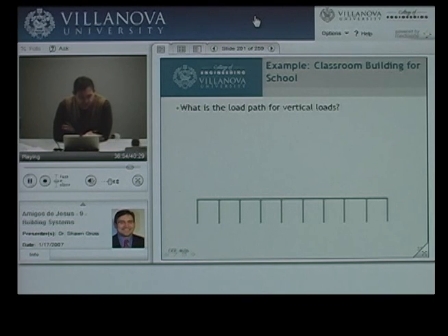I do need to consider things like where does the roof connect to your frame? Big difference in terms of the load path if the roof connects right there versus if the roof connects directly over a column. If the roof connects directly over a column, it's not going to apply any load to the beams. If it applies load to the beams, let's call these case 1 and case 2. In case 1, there's really no load from the roof going into the beams.